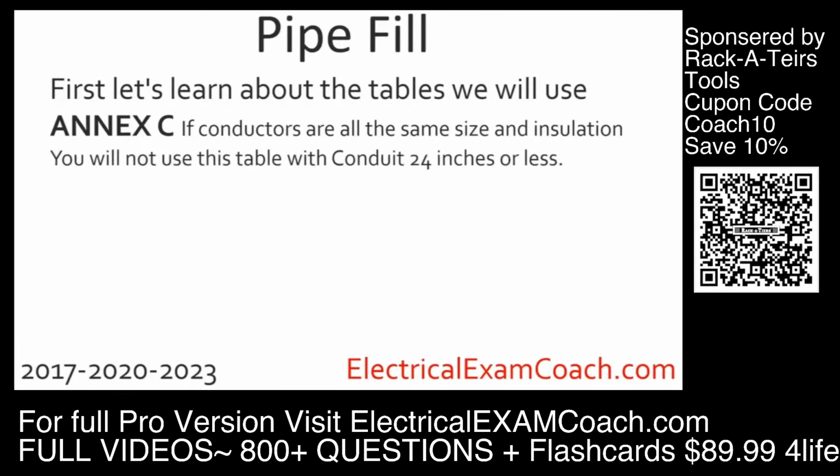Now the code book uses the term nipples, but I want you to imagine in your mind, anytime the conduit is 24 inches or less, you're not going to use Annex C. You're going to use the method that I'll teach you in lesson 7.2. You can head to page 712 of the 2017 and page 729 of the 2020. This video is 2023 compatible. You'll have to get to your page number for Annex C, and then you can follow along.